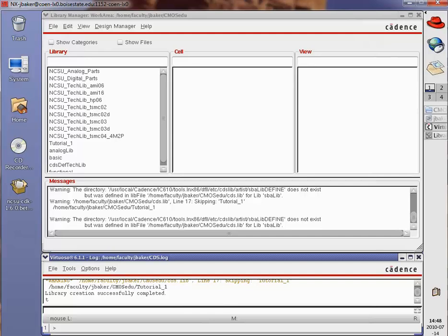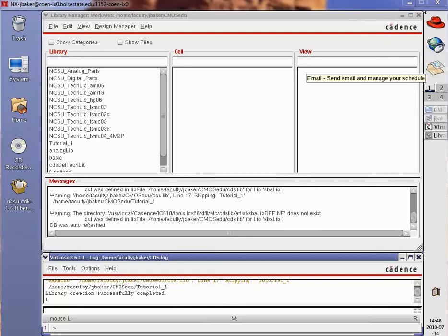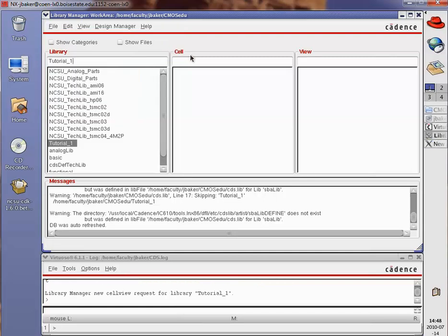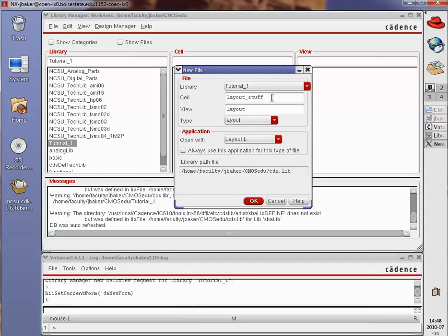minimize this. And then what we're going to do first is we're going to make a resistive divider. And so let's go select the tutorial, go up here to File, New, Cell View, and it keeps putting them behind. So let's call this rdiv and schematic.